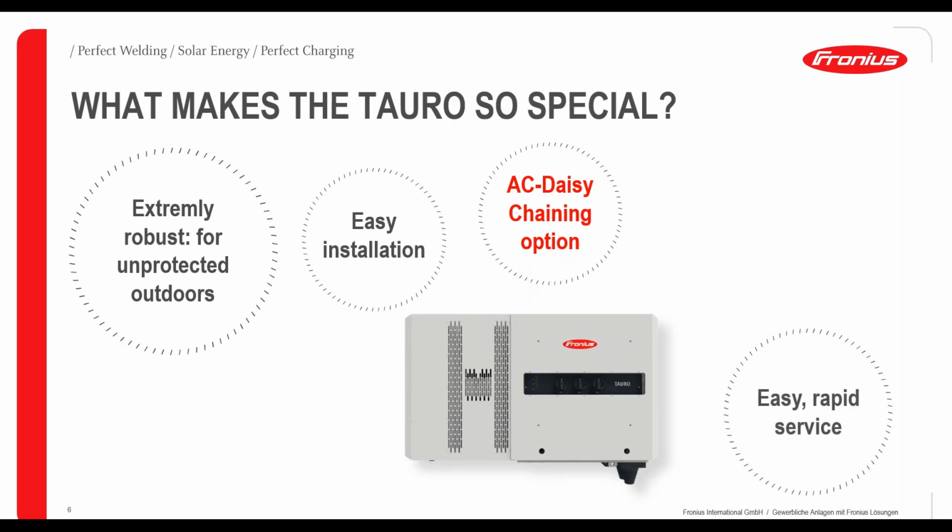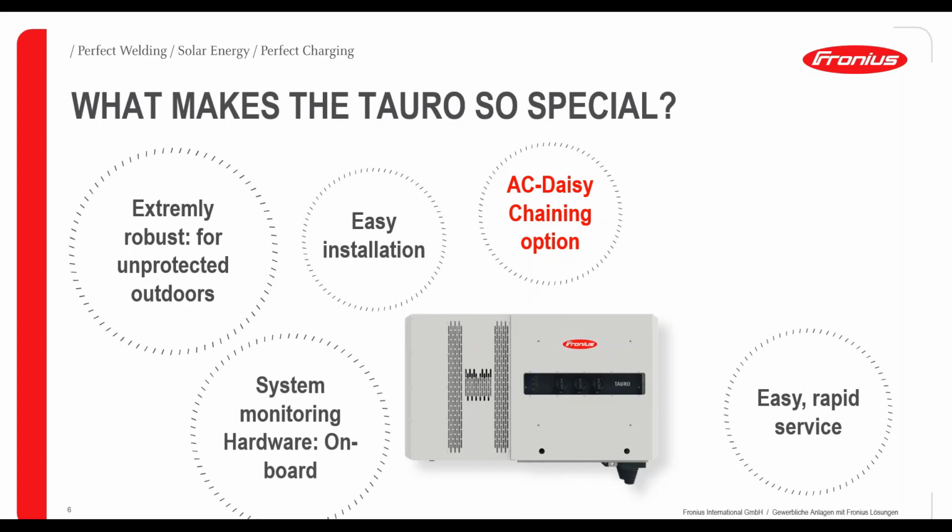Next point is easy and rapid service. Of course, as with every product at Fronius, it's on-site serviceable. So the PC boards, exchange components and so on can be exchanged by one person. We don't need to exchange the whole device, which leads to a very rapid service. Next point, system monitoring hardware is on board, of course, as standard. So we can do full monitoring on Fronius SolarWeb with all the inverters. And therefore, it's much easier to maintain the whole system.